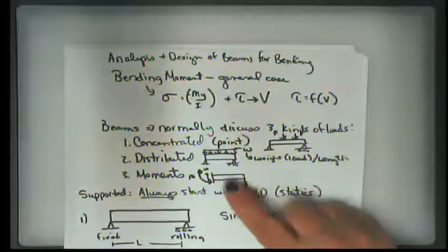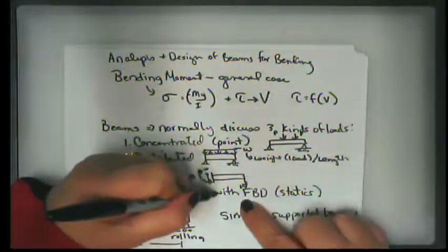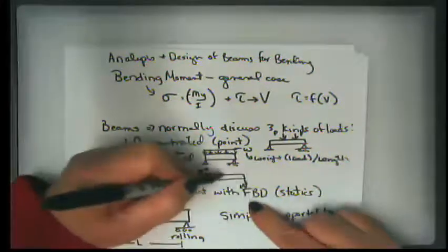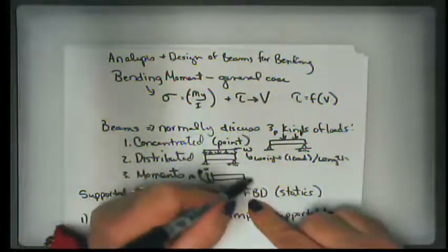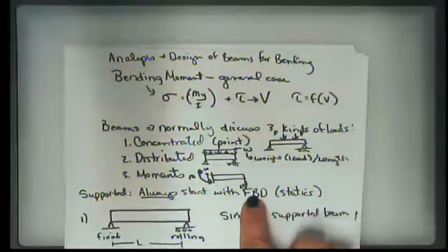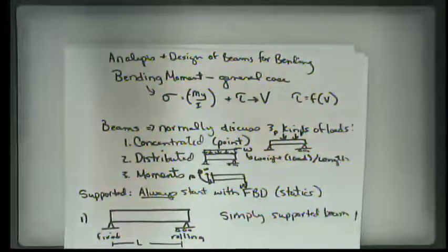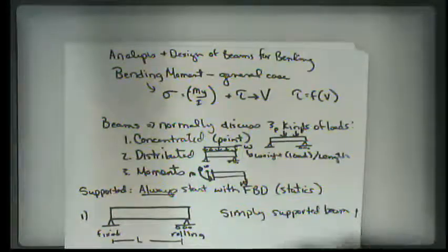Okay? So in other words, not only is the beam going to try to slide down from the wall, it's also going to try to pull out from the wall with this type of a motion, isn't it? So the wall has to counteract it with a load in the opposite direction. Or a moment, excuse me, a moment in the opposite direction.